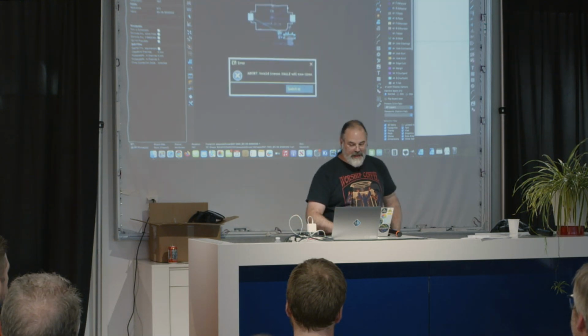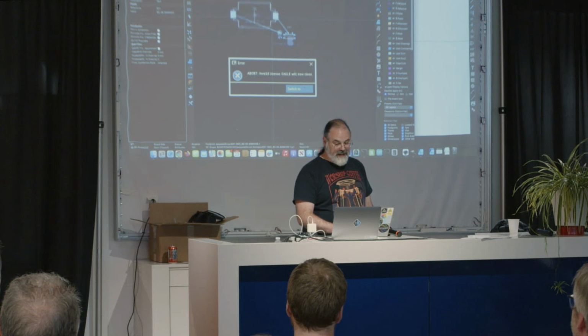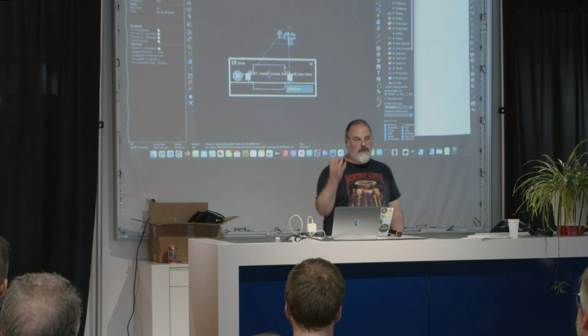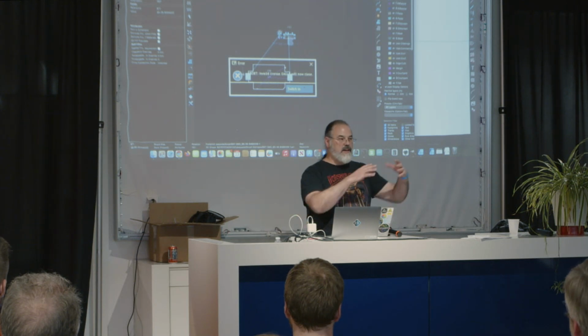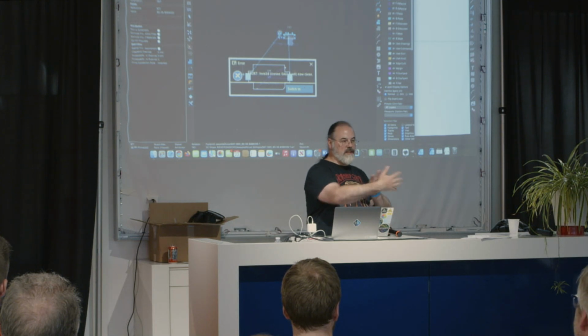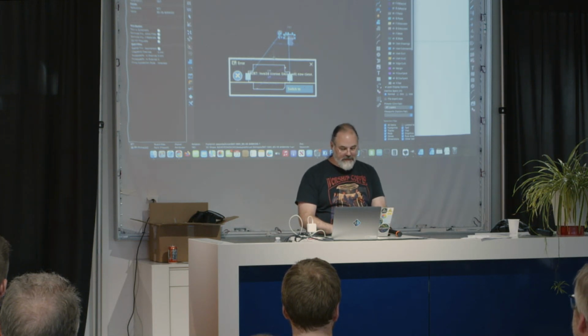All right. So we have this huge battery. Let's slot this in here somewhere. Let's go right about there, just so it's not in the way. Now, I don't know if you saw on the previous screen, but I have pulled the mask away from the front and the back of the PCB, and the PCB FR4 material is slightly transparent. So I'm going to have an LED on the back that's a side view LED, but part of that's going to be shining in, and it's going to glow through. It's a neat trick for doing glowy art PCBs.